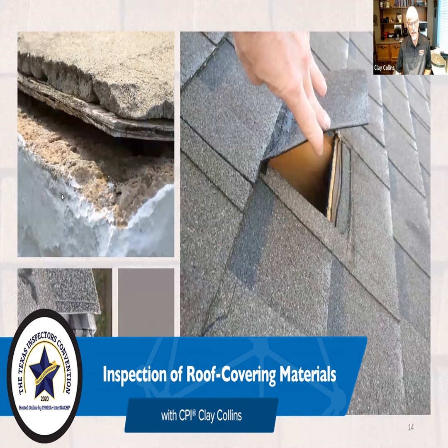You write your report and you say that there's a hole in the roof, there's a nail exposed, there's this, there's that, and then they expect a roofer to come out and find that. Well, I got into a conversation with a roofer, and he was really laying into me for that. This was during a windstorm inspection. I said, okay, what's your solution? He said, chalk. I now carry chalk, and in one of the chapter meetings here, I gave out a lot of chalk holders and chalk because I got it for free. And I carry it with me.